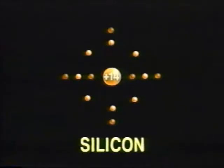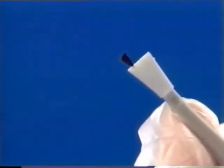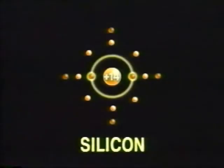Let's visualize this in another way, using something called energy bands. A silicon atom contains 14 electrons, 4 of them in its valence shell. But remember, we're examining at the atomic level. In even a very small piece of pure silicon, there are millions of individual silicon atoms. While studying semiconductor theory, it can be helpful to group together all of the electrons that exist in the first shell of all the atoms in a piece of pure silicon and indicate them like this.